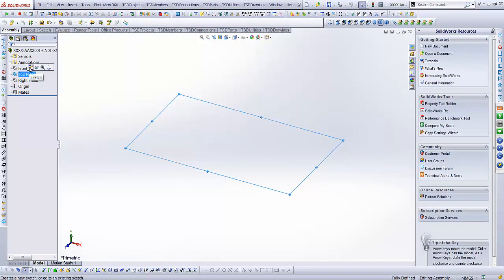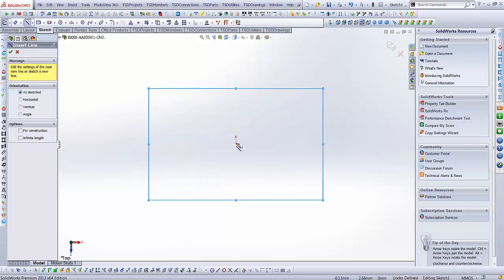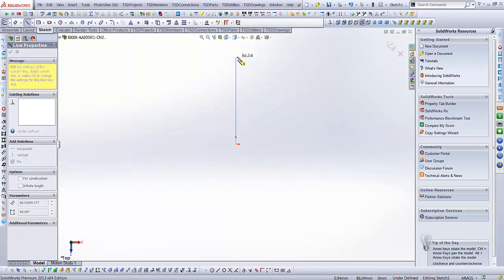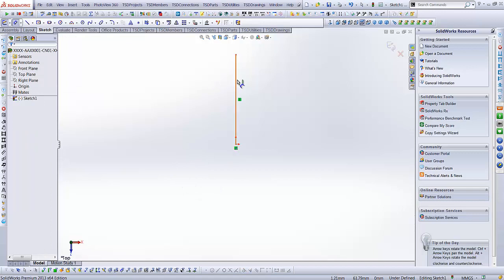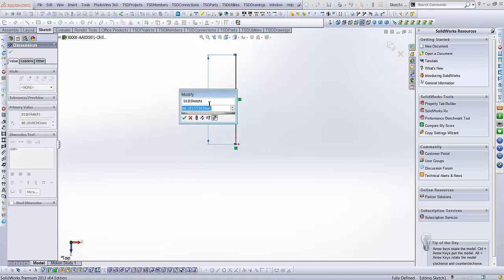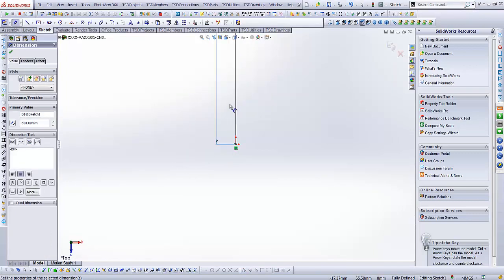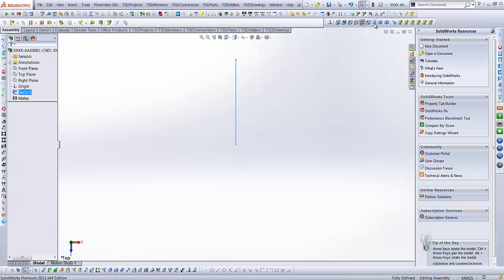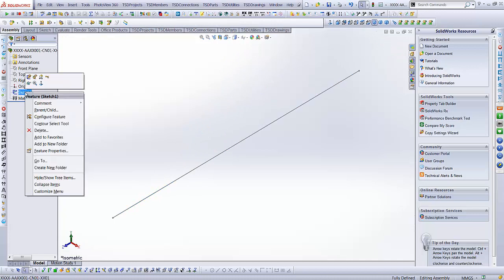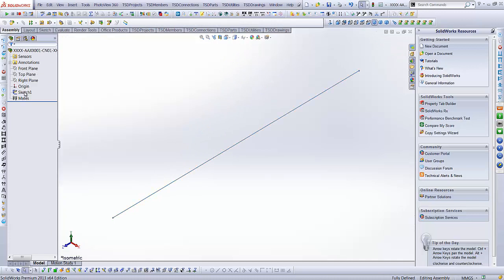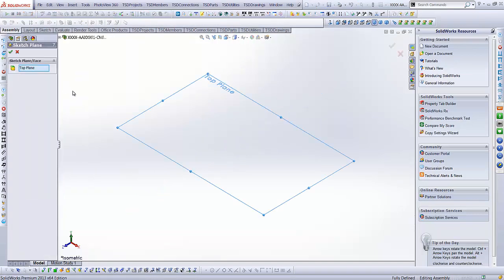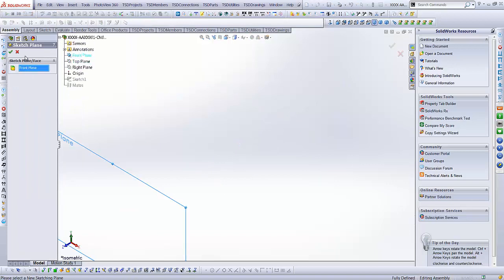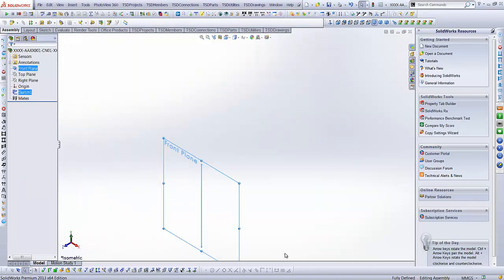Now in our base plate, depending on how we want to model connections, in this case I'm just going to draw a member sketch line which is going to drive the actual column stub, and I'm going to give it a 600. Actually I might make it a little bit smaller, it's too big. Okay, and this is our member sketch, or I've stuck it on the wrong plane, which is really good because then I can show you how you can actually shift your sketch from one plane to the other. In this instance I want it on the front plane, and it's flipped it.